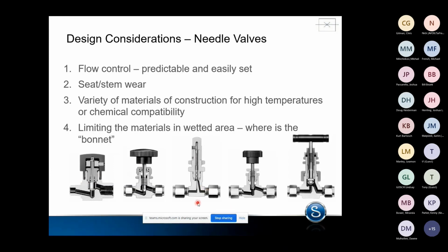This valve in the middle here is a metering valve. That's where you're seeing that very fine needle-like stem. This is for fine metering applications compared to this much coarser V stem tip. So it's designed only for flow control. This is not able to do on-off applications. It cannot isolate. You look at the surface area in here, you're going to create a very high friction force trying to close that. And usually what you see is you'll be able to close it, and when you reopen it, it snaps right here.